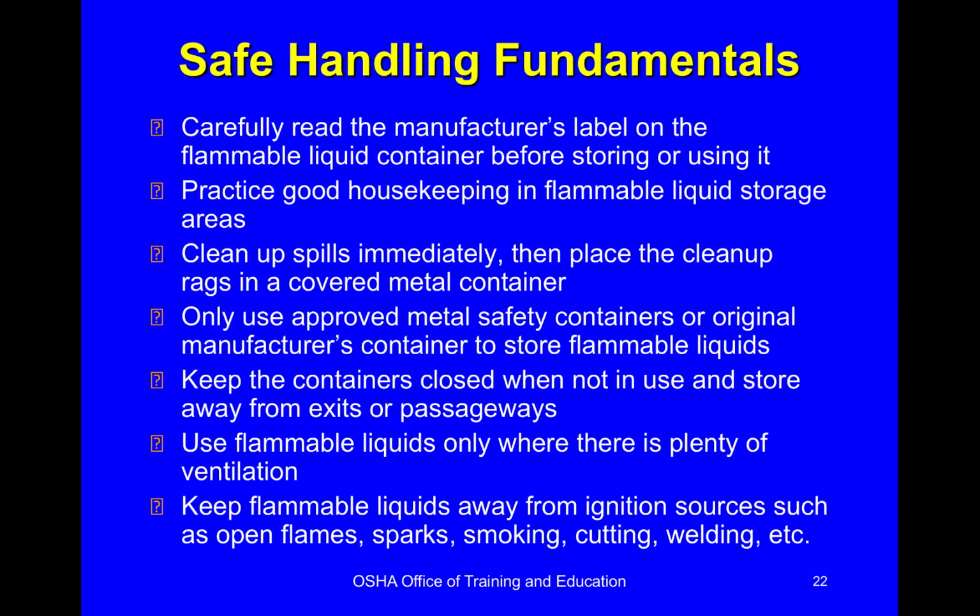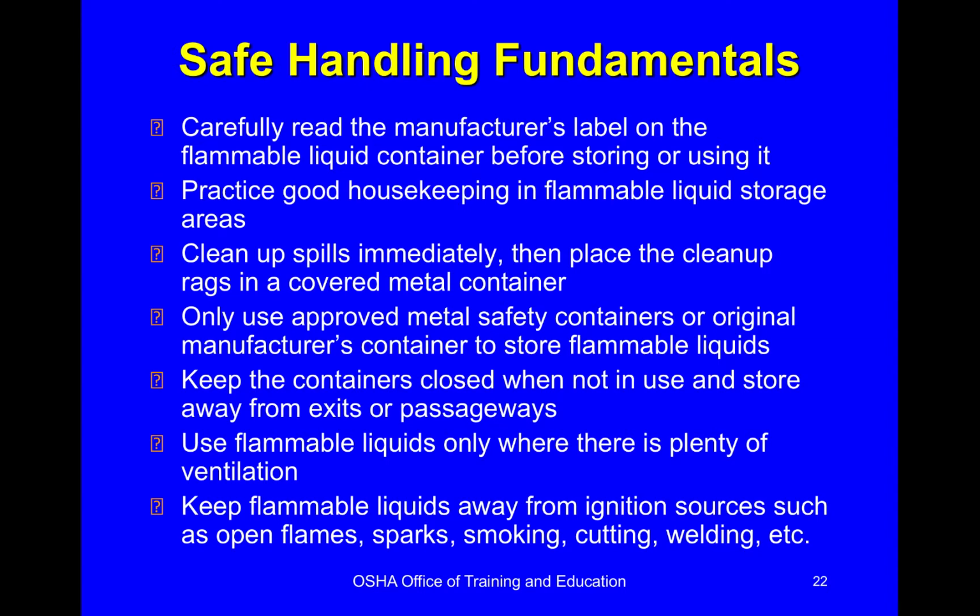Safe handling fundamentals include: you need to carefully read the manufacturer's label on a flammable liquid container before storing or using it. Practice good housekeeping in flammable liquid storage areas. Clean up spills immediately and then place the cleanup rags in a covered metal container. Only use approved metal safety containers or original manufacturer containers for flammable liquids.